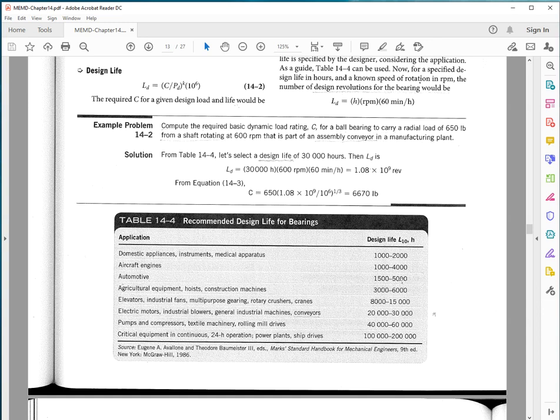Again, it depends. For aircraft engines, you have periodic inspection and engine rebuild, and they can afford to go with shorter design life. That means lighter weight, but requires more frequent diagnosis and preventive replacement of components.